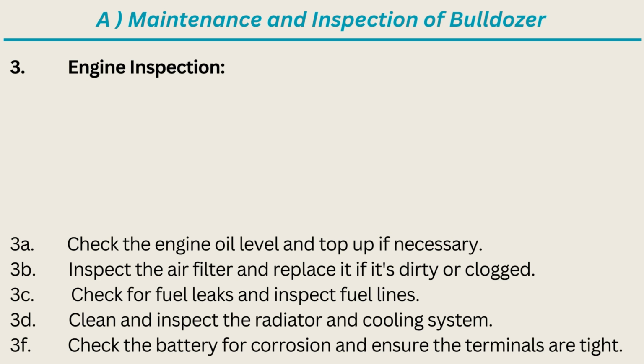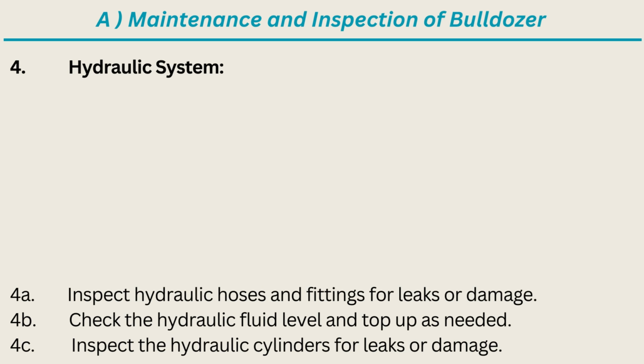3C. Check for fuel leaks and inspect fuel lines. 3D. Clean and inspect the radiator and cooling system. 3F. Check the battery for corrosion and ensure the terminals are tight. 4. Hydraulic system. 4A. Inspect hydraulic hoses and fittings for leaks or damage.